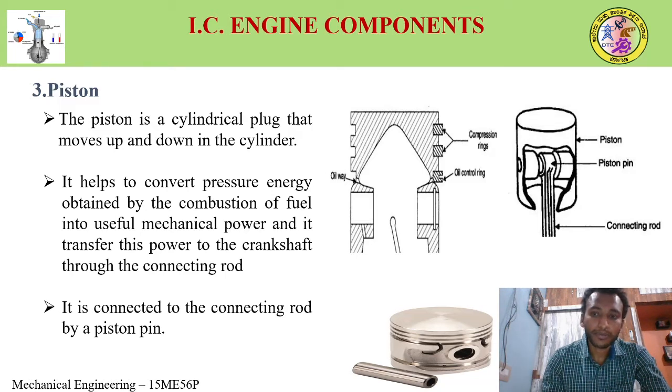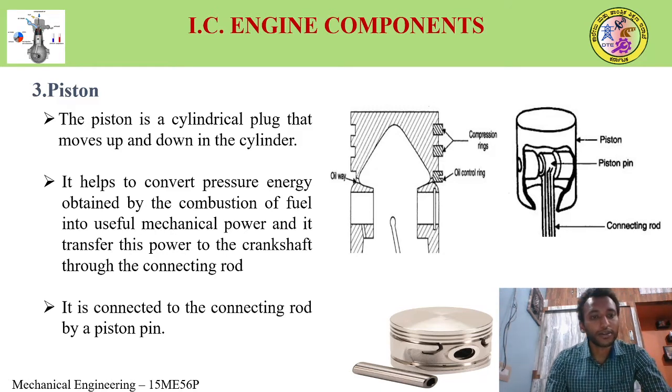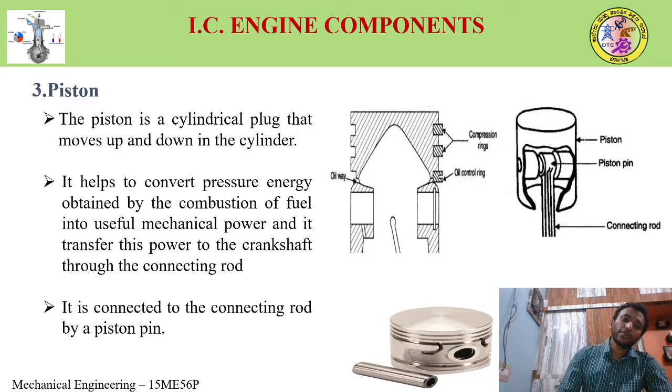The top position the piston reaches is TDC, top dead center, and the bottom position it reaches is BDC, bottom dead center. Its function is to help convert the pressure energy obtained by the combustion of fuel into useful mechanical work.